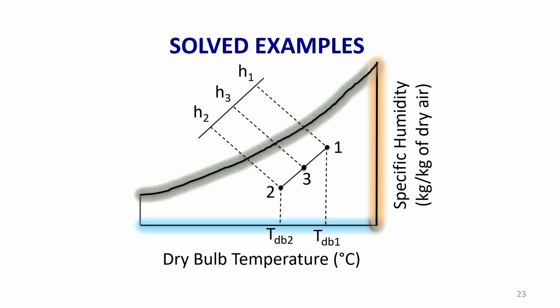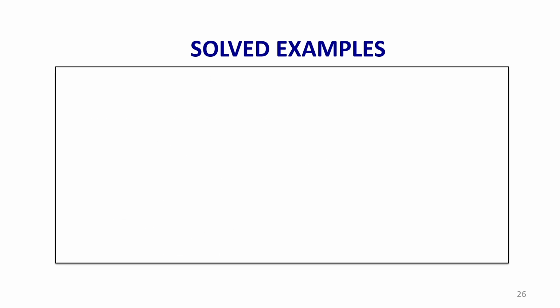Okay. So, I have not shown this one in that summary of processes. Here, as you know, the dry bulb temperature is here, and the specific humidity on the right side. There are two air streams. Let me plot this in the form of a diagram. One air stream is coming like this, state point 1, another air stream is coming like this. So, both are mixing and you get another air stream.